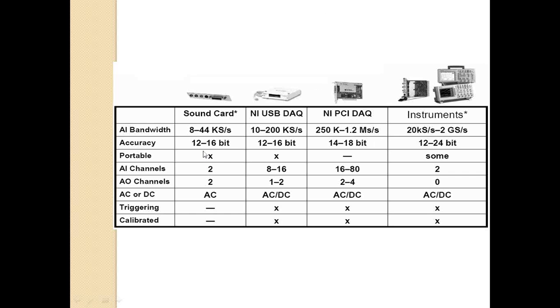If you compare here, based on your application you can choose your hardware or DAC. For example, if you are just acquiring 2 to 3 sensor data where sampling is not mandatory, you can go for hardware with a lower sampling rate. But when you need much more precise sampling, such as signal processing or acquiring real-time data where even a single sample matters, you can go for a high-end sampling DAC, where you'll be able to sample each signal more precisely than your NI myDAQ or your sound cards.